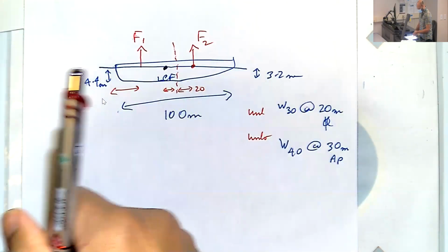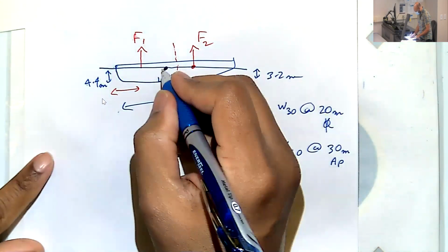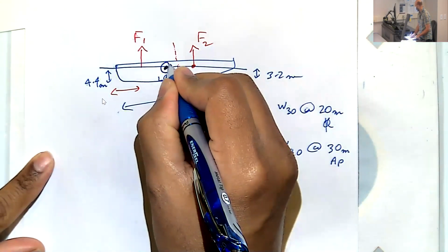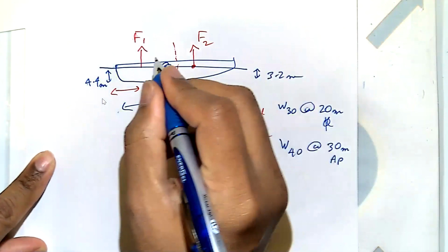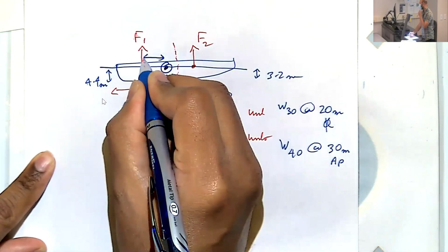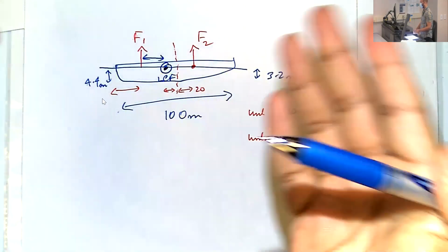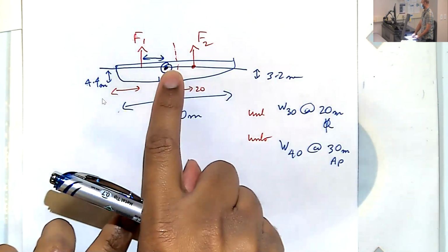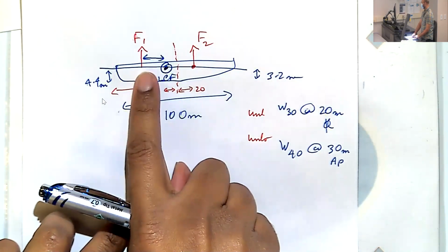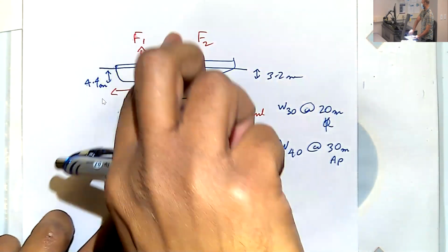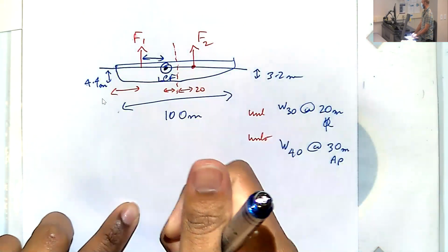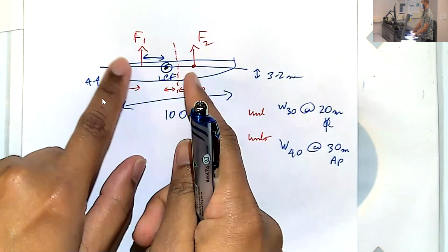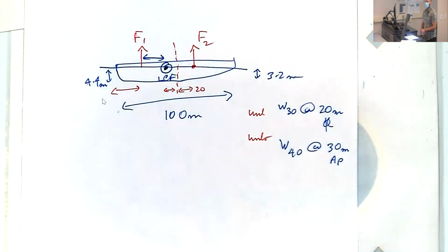Okay. You're confusing yourself. It's simpler. Always you have to compute moment about the LCF, okay? So you always need to find this distance. Whether you subtract, add, that's easy, right? So always moment about the LCF, okay? Whether you give a positive sign to the moment or a negative sign depends on whether it's clockwise or anti-clockwise. So here it seems we will have opposing moments. So one will get a negative sign, the other will get a positive sign. Okay, make sense?